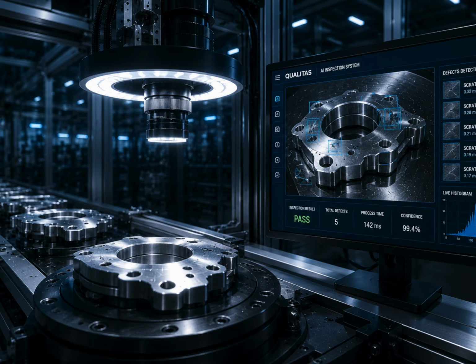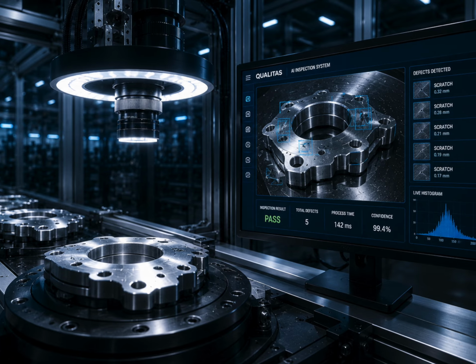Most engineers, when a vision system starts missing defects, will look at the model, the thresholds, the software configuration. Lighting is usually the last thing to check, because it's not obvious how to check it, and because it was working fine when the system was commissioned. But lighting changes, and the change is usually slow enough to be invisible. Now there are 4 questions that you need to ask.